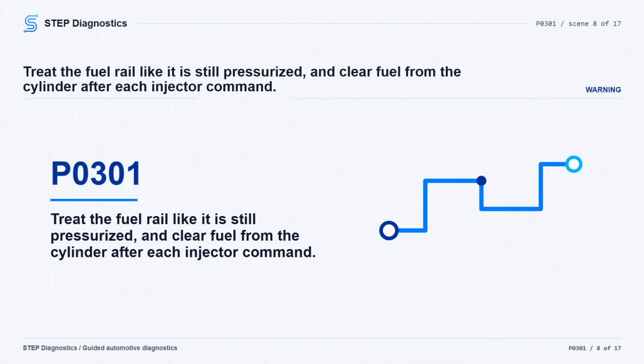For the injector check, use fuel pressure decay tester 8978A at the fuel rail. Before opening any fuel line or fitting, release fuel pressure. This system can stay under pressure even with the engine off, and that is a serious safety concern. Key on and let rail pressure reach maximum and stabilize. The ignition may need to be cycled off and on a couple of times to reach maximum fuel pressure in the rail. Record that as the starting pressure.